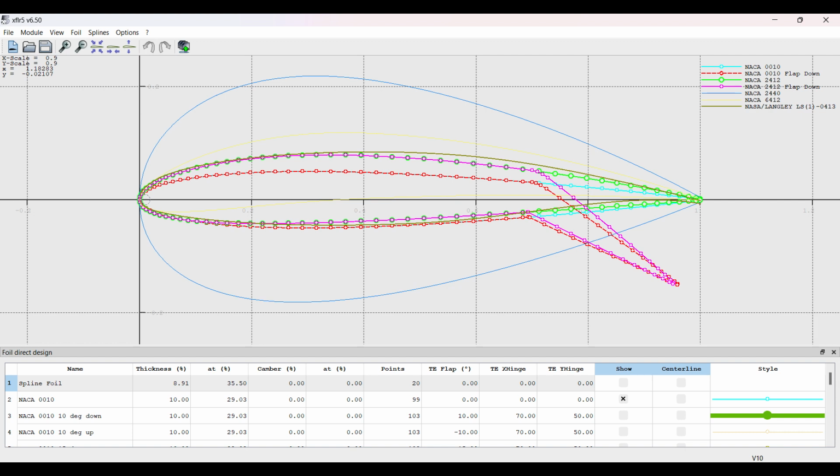Here are the author's recommendations regarding airfoils. Airfoils should be no more than 6% thick, have 5% or less of camber, and have maximum thickness at 25% of chord. A camber of 3% gives the best lift-drag ratio. A camber of 5% gives the best maximum lift. A normal airfoil is dangerous if the center of gravity is moved beyond 33% of chord.